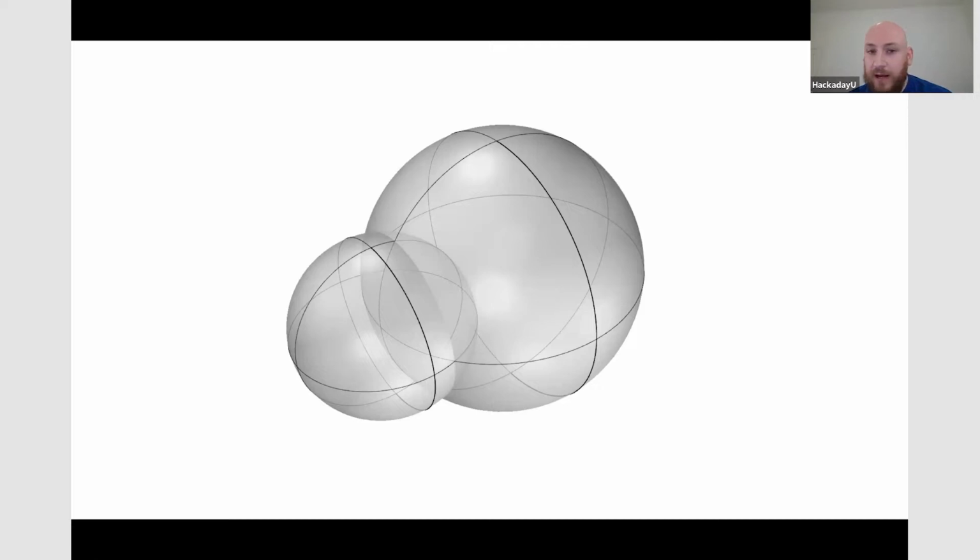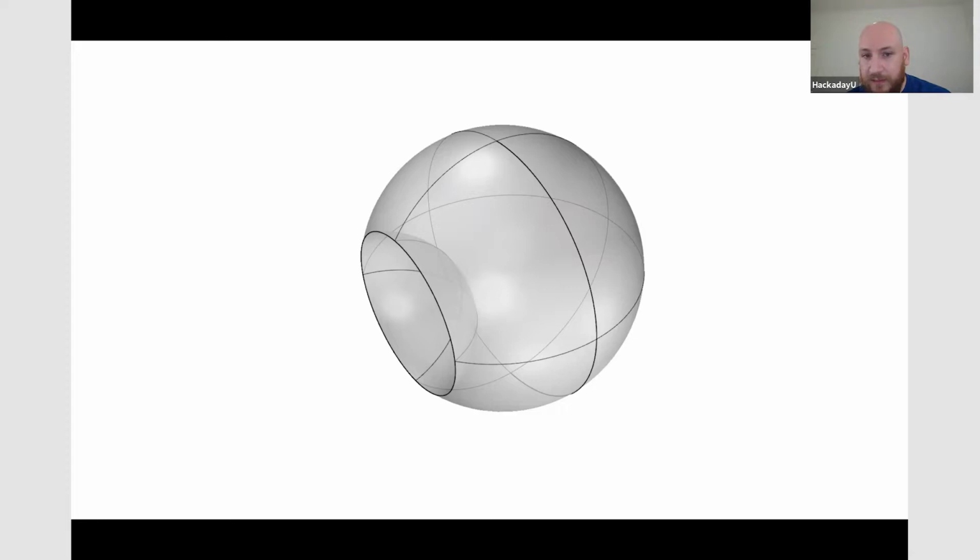The only way Rhino will deal with solids interacting with other solids is when their surfaces are actually intersecting with each other and touching. So if I did this small sphere and large sphere, and I did a Boolean subtraction, the volume of the small sphere would cut away from the big sphere, and I would end up with this sort of Star Wars Death Star-like shape.